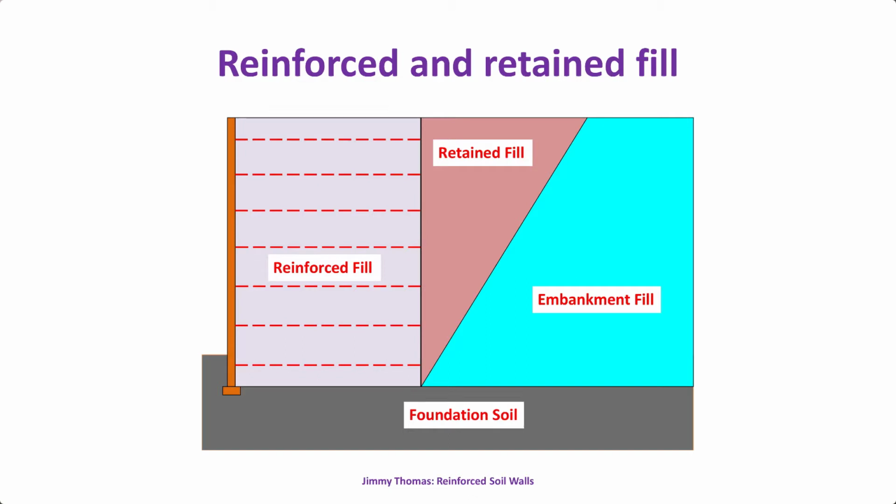Then this is now our retaining wall. So this retains this soil. Again, this applies earth pressure on this block. So again, we need a reasonably good quality soil here. May not be as good as that, but still the property is important. Behind this zone, this has no effect on this wall actually. So normal soil can be used.